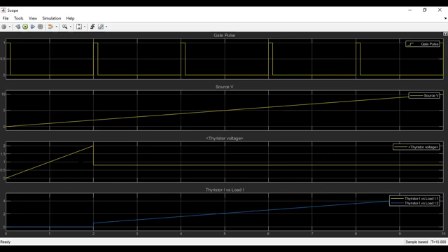Let me explain the graph along with the theory. From here to here, see this increasing curve shows the forward blocking mode of the thyristor, the mode where it doesn't conduct. The current is flowing, but it has not started to conduct yet. At this point, the junction 2 breaks. Hence, the voltage drop occurs. From here to this is the voltage drop.